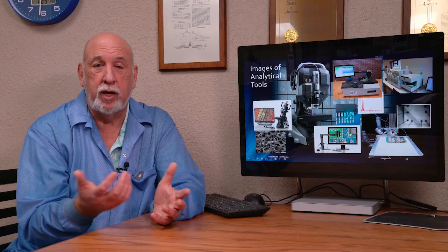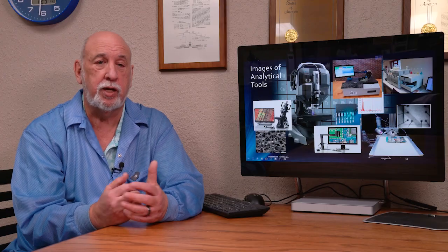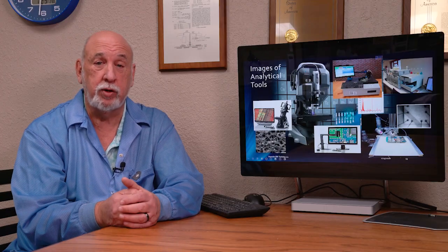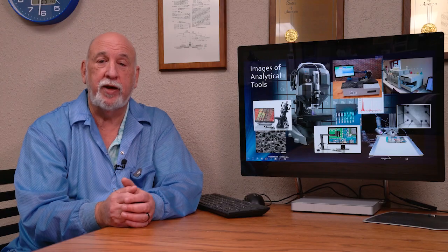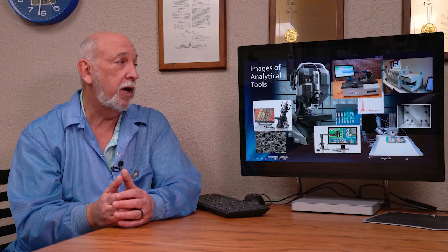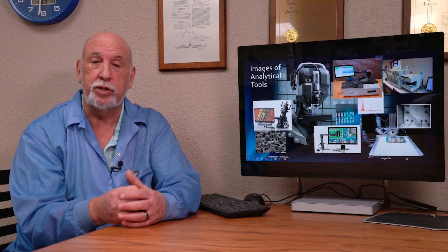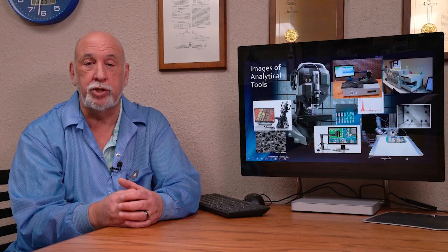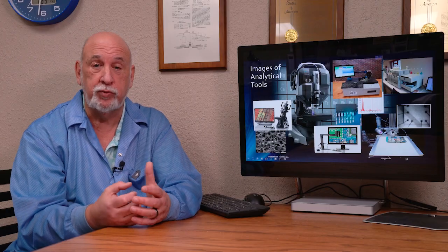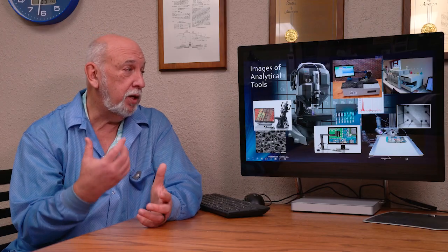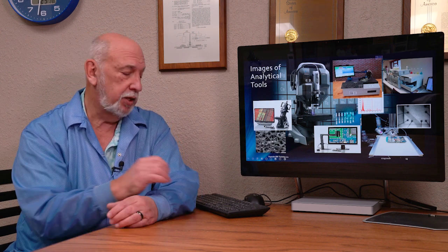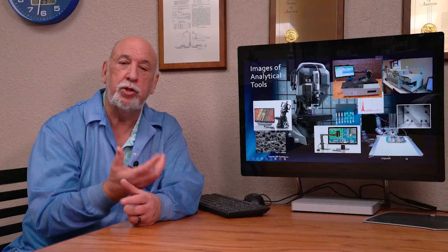Some of the tools that we use for analysis start with optical imaging, using Keyence microscopes and Tagarno low-mag microscopes. We're able to see the effects with some of those, and with X-ray. We use localized C3 ion chromatography analysis to determine how much contamination is in a 0.1 square inch area with a very small extraction volume of 2.2 mils. We use FTIR, XRF, SEM, EDX. So some traditional tools, but also some new, unique tools.